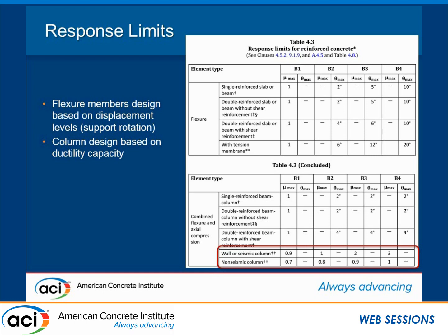And the basis of this design is what's the ductility defined as first yield of the column. And if we have a non-seismic column after this first yield occurs, then we're starting to get the point where we're going to lose compression concrete, bars won't be supported, we can get buckling and following with collapse. So a non-seismic column is limited in the worst possible case to a ductility ratio of 1.